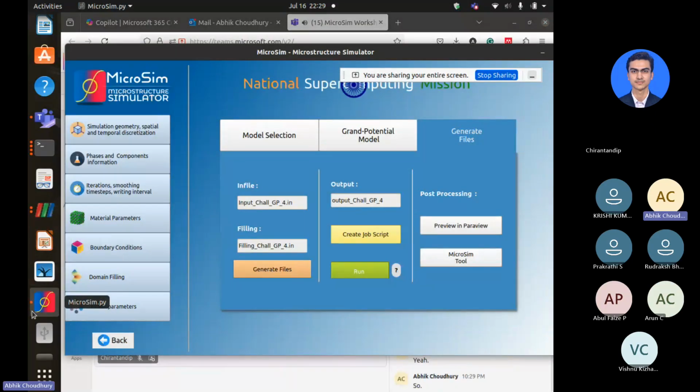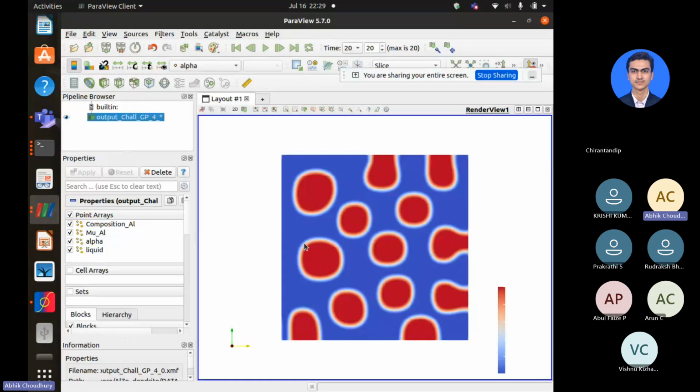So let's go back here. I assume that most of you have got it until here, right? And so let's look at these things over here. Remember in your input file, I told you to make a change with respect to the random filling, which is what you did, and you got a random distribution of precipitates, or well, grains. What you have given is a 45-degree rotation to your anisotropy, which is why all of your shapes are looking cubic. Okay, that is the reason they are looking cubic. Otherwise, if I had given isotropic, they would have remained circular. Isotropic means the anisotropy is 0.